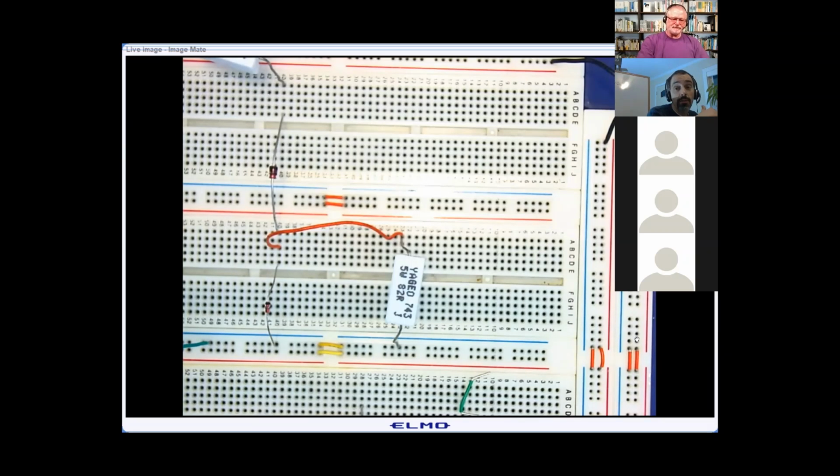They will see what goes on in the circuit, and they'll keep that voltage really at that 4.3 or 6.2, whatever it is, exactly, all the time. So the resistors, to put it another way, will consume some of the voltage, but if you have an uncertain or varying input voltage, you're going to get an uncertain or varying output voltage past the resistor, whereas with the Zener, you either get what you're supposed to get or you get nothing. That's correct, yes. Absolutely. Got it. Thank you. You're welcome.